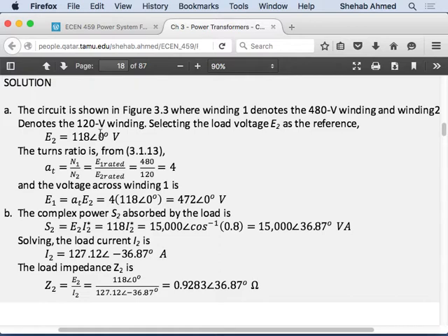But what does voltage reference mean? Say I started this generator, and then 1 millisecond later I started a second generator right next to it. The phase angle is really about when this one started versus when that one started, so take one as a reference. That's why, when we simulate bigger power systems in PowerWorld, we will always have a reference.